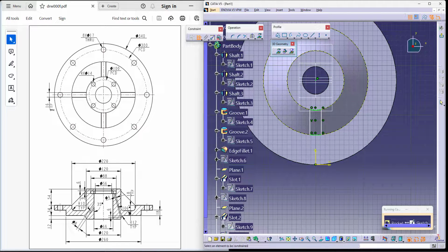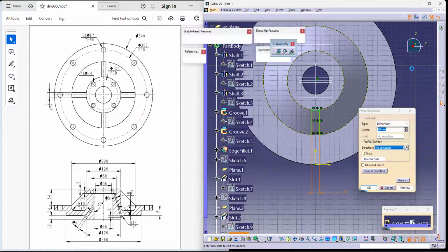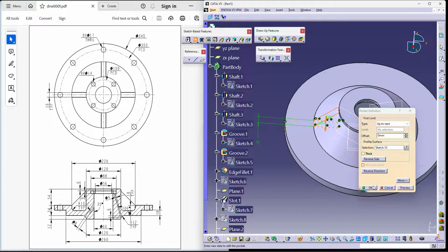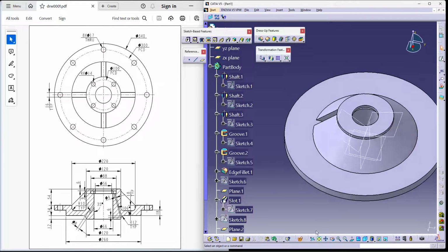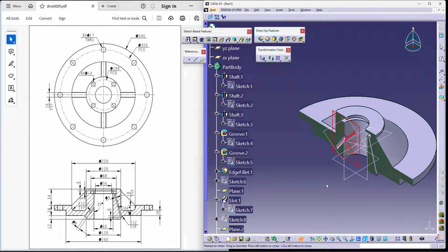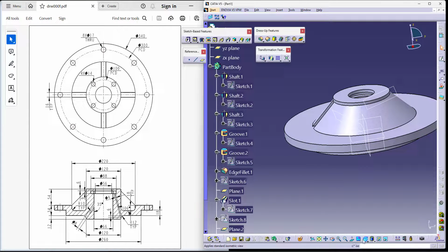Now the distance between these two is actually given as 16. It's typical, that means it's the same for all the 4 sides. And when I exit, you can start removing the material. The material should be cut towards the other direction up to the next surface it can find, and you will be seeing the cut. This is how it actually looks like. You can again check your dynamic sectioning view and also see how it looks like. You can see the slant cut. Here you will obviously not be able to see the material. This is how it is supposed to look like.